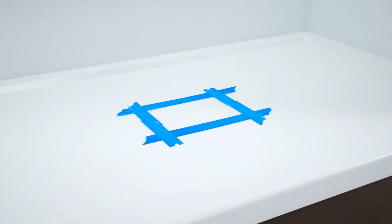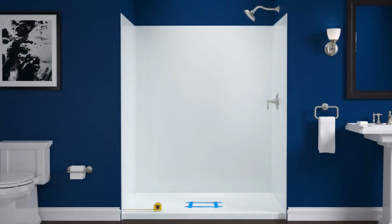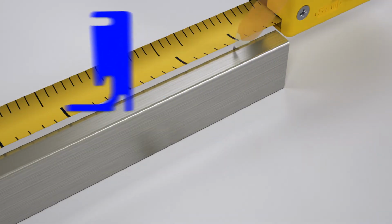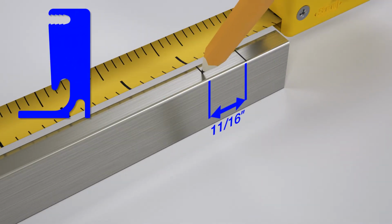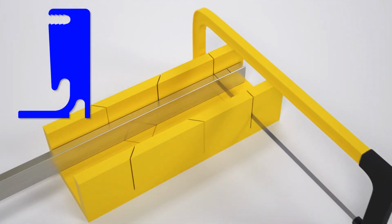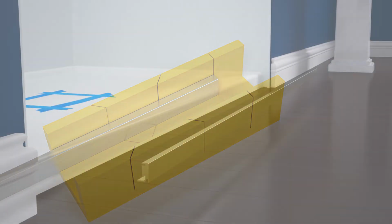Cover the drain with tape to avoid the loss of small parts. Measure the distance between the walls along the shower ledge. Mark this distance on the threshold. Make a second mark 11/16 inch to the inside of the first mark. Cut the threshold at the second mark and file any rough edges.